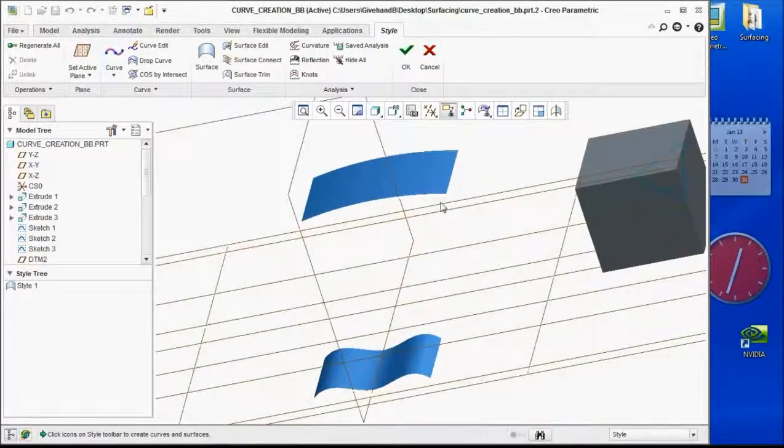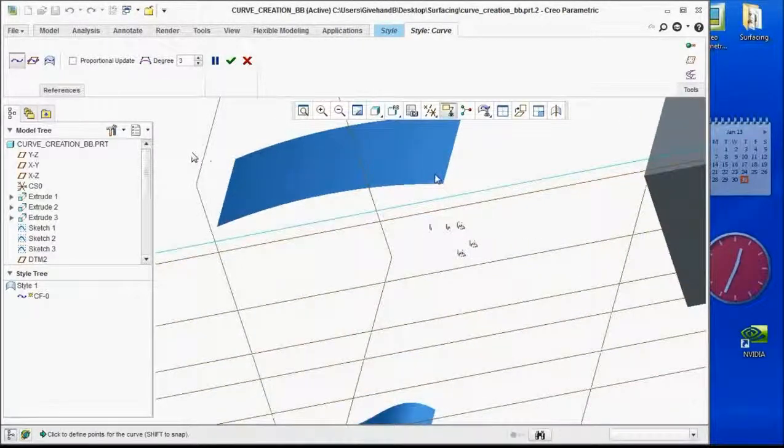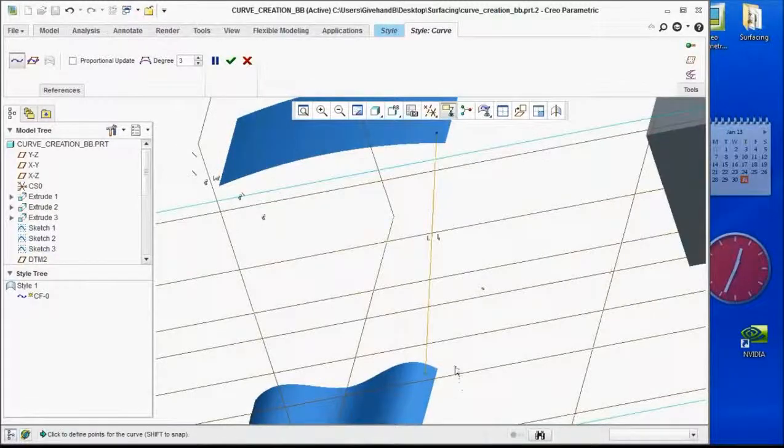And so what I'm going to do is something fairly the same. I'm going to come in and say I want to create a curve. Now, when you create a curve in the ISDX tool, you have essentially a 3D curve, or what is called a free curve. You have a planar curve, which is a 2D curve, and then you can drop a curve on a surface just by picking points on the surface. So I'm going to create a curve, pick this surface, and pick right about there, okay?